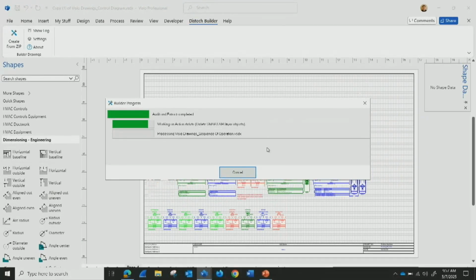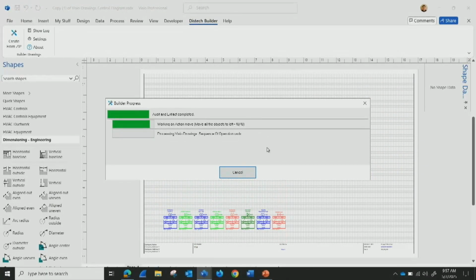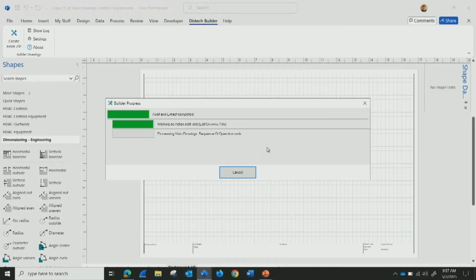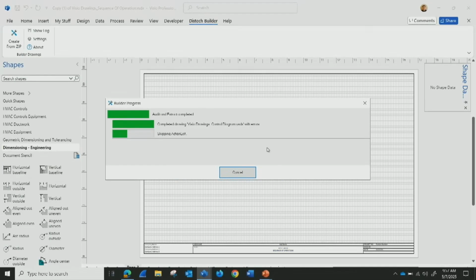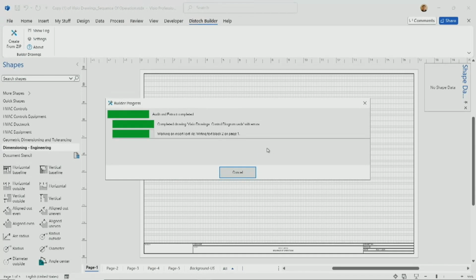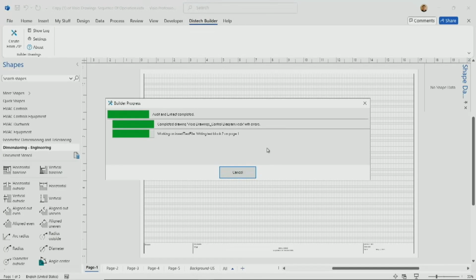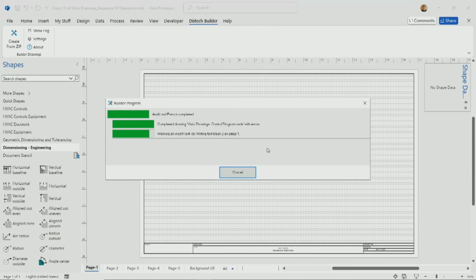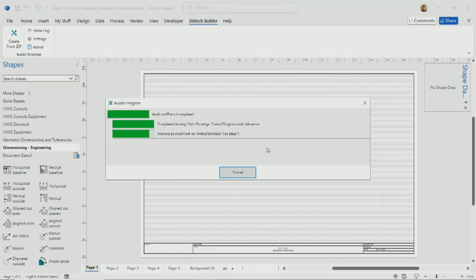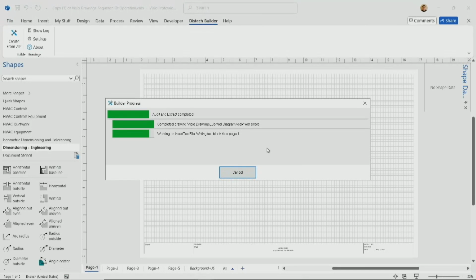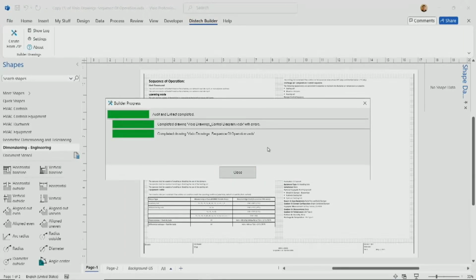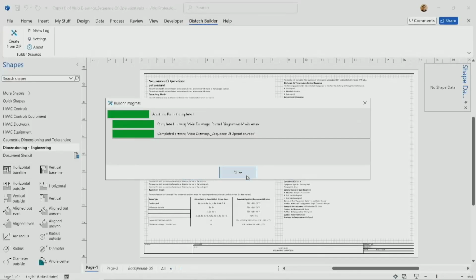So anyway, if you're doing a VAV, this takes maybe 3 minutes, the whole process, depending on your choices. And if you decided to use your own code, you may be adding a little bit of time, but it's fantastic because one, you're telling the technicians what you want to use. When they go to troubleshoot it, they know what to expect. It's not a surprise. And you're maintaining the quality of your programs, right? One place. You shouldn't have everyone with their own versions of a VAV. All right, so it's done.